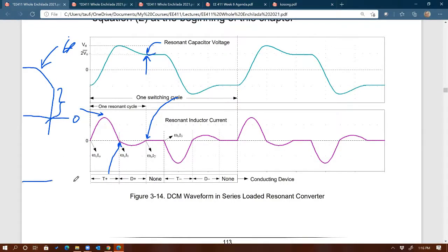A Schottky diode is a fast diode. Reverse recovery is very short, like tens of nanoseconds, compared to PN that has around hundreds of nanoseconds. So like a factor of 10 faster.